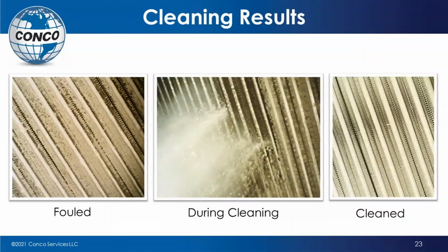In the end, what you're looking for are clean tubes. And if you remember the picture I showed you before on the left, the fouled fins of that particular unit, you can see it's the same picture. That's what we've got. During the cleaning itself, you can see the pressure coming through. And notice the contrast. On the upper left side above the water, you can see how it's clean. Whereas on the right side of that picture, you can see that the unit hasn't been there yet, and that's still fouled. So you can see right there the contrast of how the unit is working, how it's able to clean and drive all that debris out.